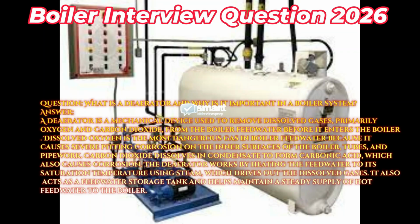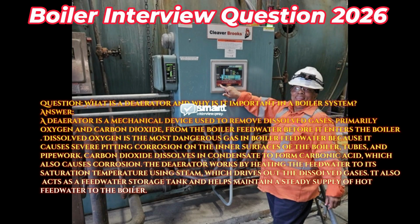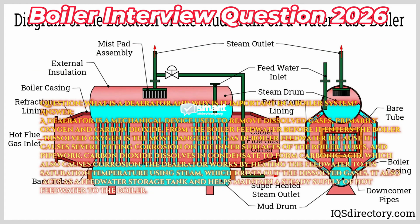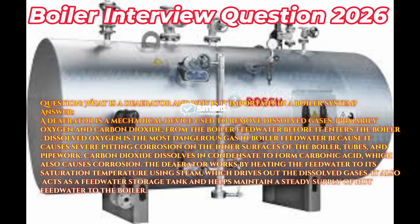Question: what is a deaerator and why is it important in a boiler system? Answer: a deaerator is a mechanical device used to remove dissolved gases, primarily oxygen and carbon dioxide, from the boiler feed water before it enters the boiler. Dissolved oxygen is the most dangerous gas in boiler feed water because it causes severe pitting corrosion on the inner surfaces of the boiler, tubes, and pipework. Carbon dioxide dissolves in condensate to form carbonic acid, which also causes corrosion.